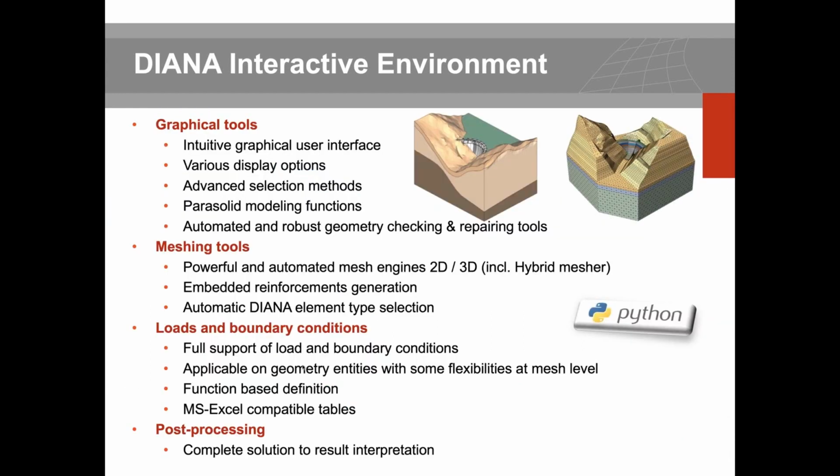In terms of graphical tools, Diana IE offers an intuitive user interface with various display options and advanced selection methods. Modeling functions are based on Parasolid, and it also has automated and robust geometry checking and repairing tools, which is also very good when you deal with CAD models.